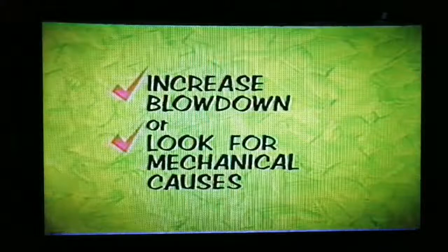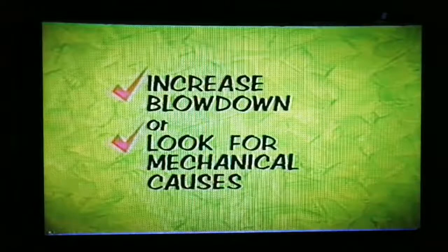If a valve has popped and blown down an appreciable amount, but will not close tightly, it is an indication of mechanical interference or an excessively low blowdown adjustment. If increase in blowdown does not correct the trouble, the valve should be taken apart and inspected for mechanical defects.